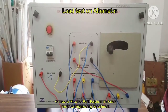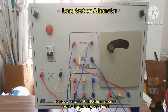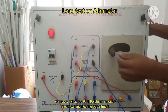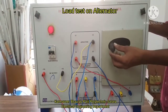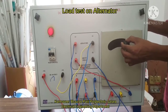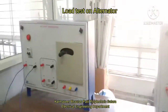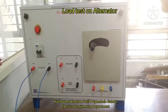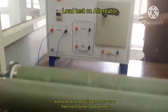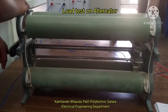So students, now with the connected resistive load, we will make the motor on. For that, first put on the main switch. After that, rotate the handle of the 3-point starter. Initially it was off, now it will be on. So the motor will be started. We have already adjusted the speed to 1500 rpm, and now we will start the alternator. For that, first put the exciter switch on and then increase the excitation.